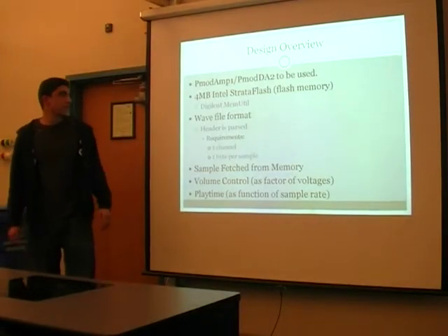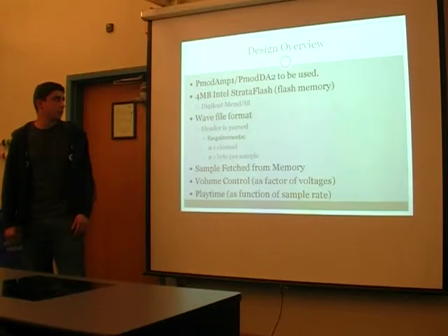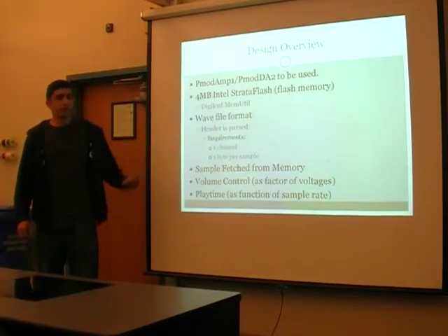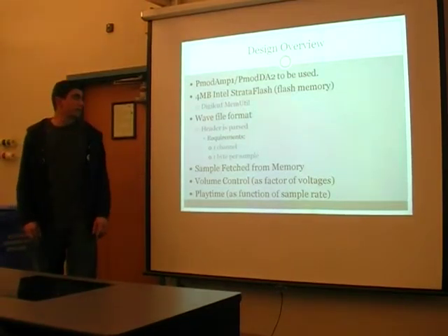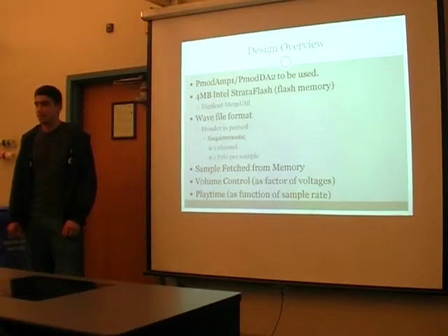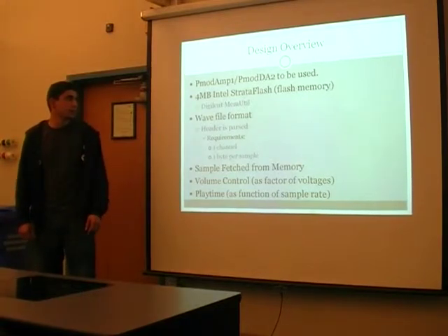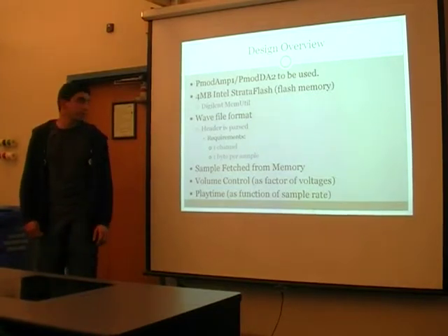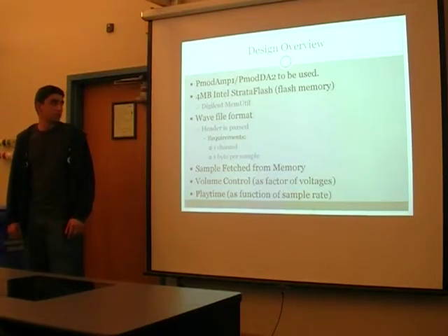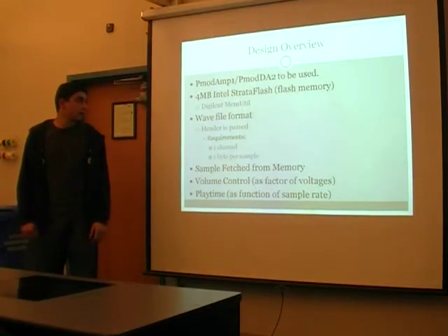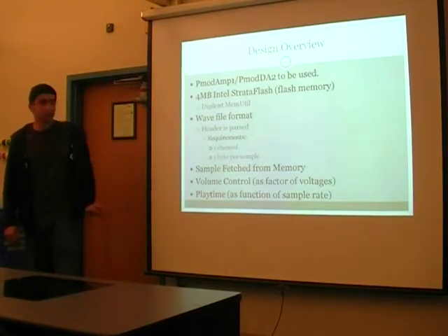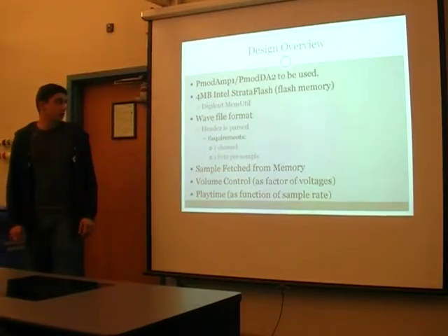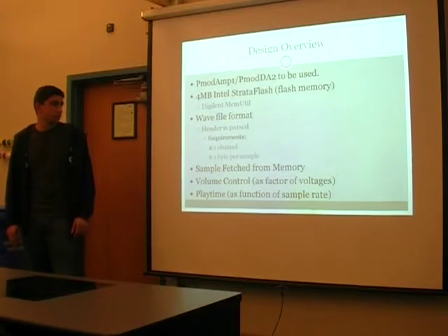As mentioned before, we use a digital analog converter, and attached to its output was a PMOD amp. This one takes in the analog signal, and on the other end is a standard headphone jack, so we can just plug in a computer speaker. The Nexys One only has 4 megabytes of flash memory, so we couldn't store more than one song. I used a utility by Digilent called MemUtil. That's how I flashed the memory in the first place, with a WAV file from the computer through USB.